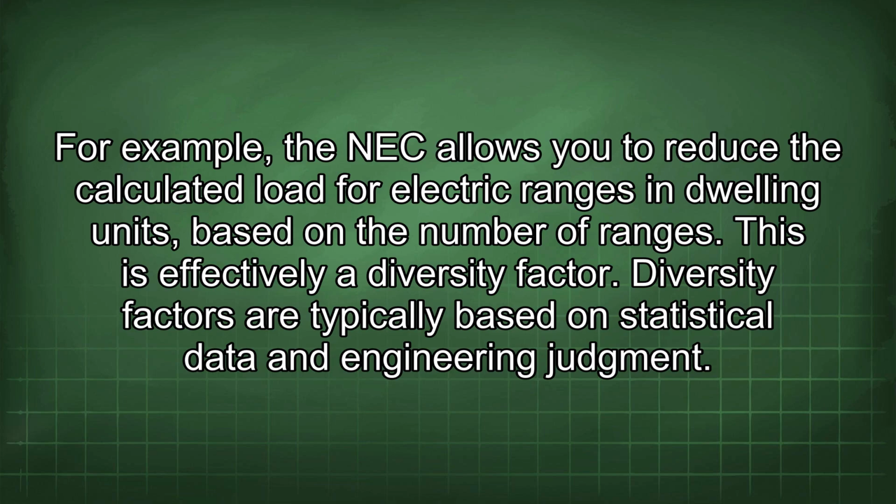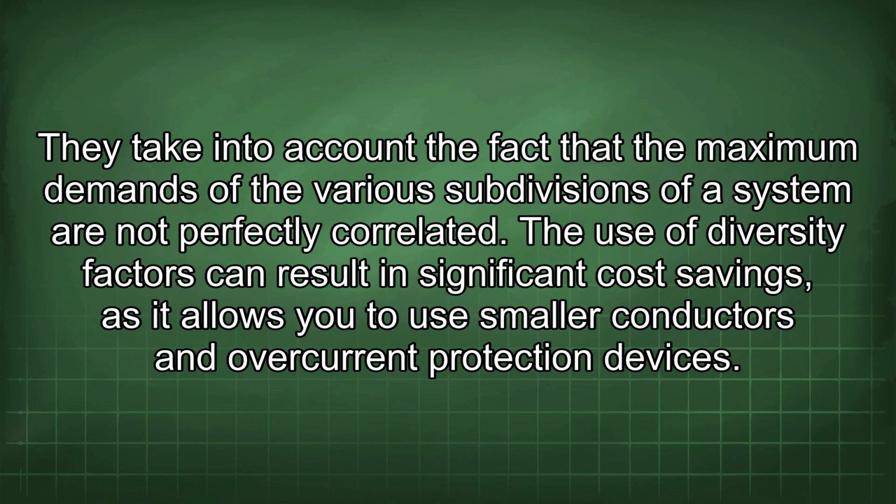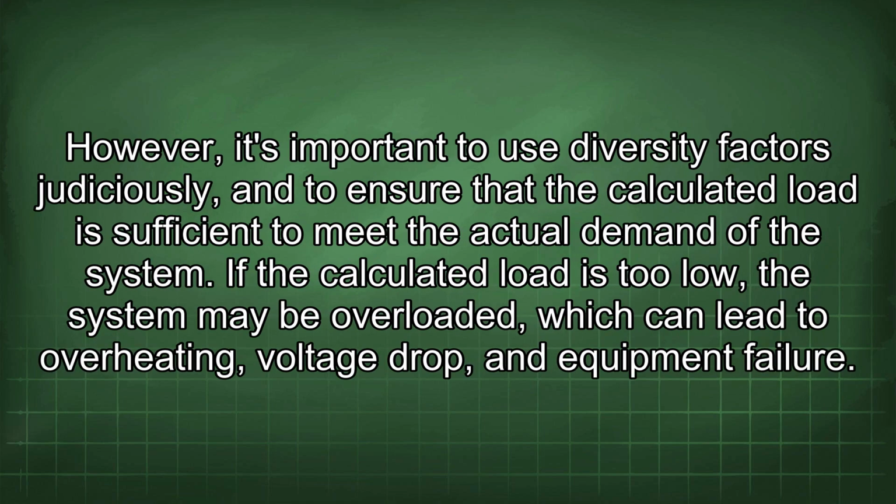Diversity factors are typically based on statistical data and engineering judgment. They take into account the fact that the maximum demands of the various subdivisions of a system are not perfectly correlated. The use of diversity factors can result in significant cost savings, as it allows you to use smaller conductors and overcurrent protection devices. However, it's important to use diversity factors judiciously and to ensure that the calculated load is sufficient to meet the actual demand of the system. If the calculated load is too low, the system may be overloaded, which can lead to overheating, voltage drop, and equipment failure.